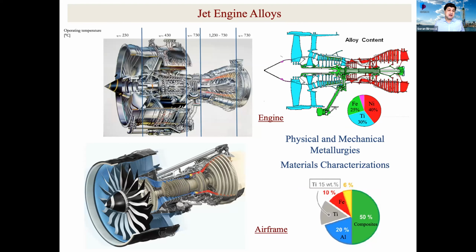For example, I work on the materials used for the blades in the jet engine, which is titanium 64. This material is exposed to temperatures; the maximum it can be exposed to is about 450, or they said 500, but we wanted to be below that operating condition for safety reasons. I also work on titanium 62, the titanium used on the compressor side for the disc and also the blade.